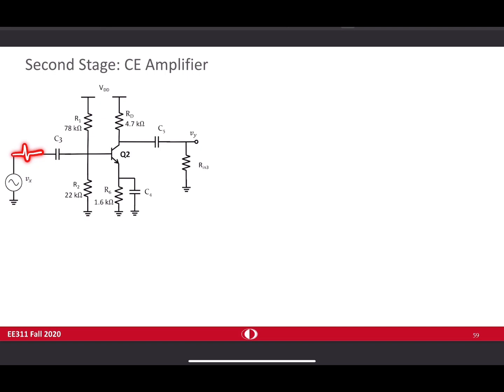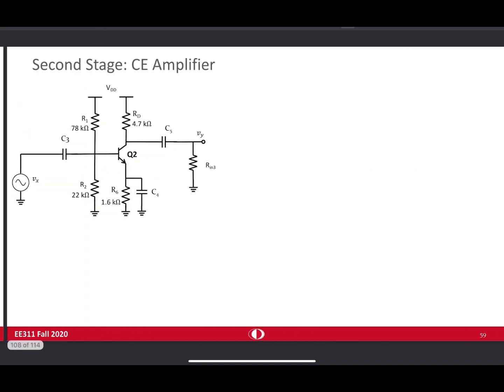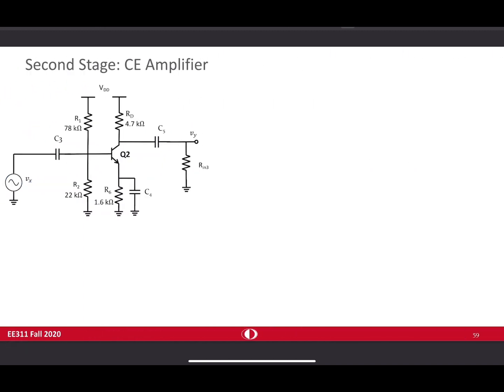Sometimes your friends or some of the students may confuse it. They can think that the output resistance that you see in here should be included as the source internal resistance, but it is not correct because Vx directly appears at this node, and it does not have any voltage drop across Rout1. So Rout1 appears like a parallel resistance in here. So you don't need to take it into account. It's already given in this voltage. This voltage already includes the effect of Rout1. So you never use a source resistance in here.